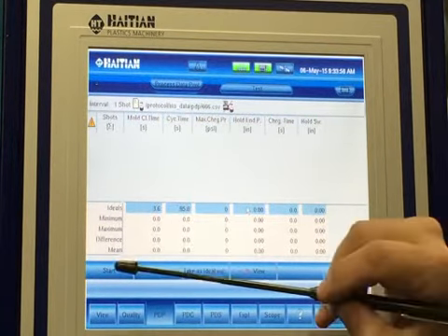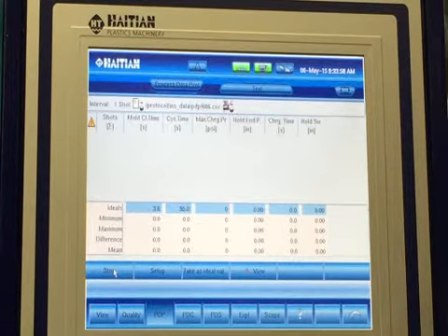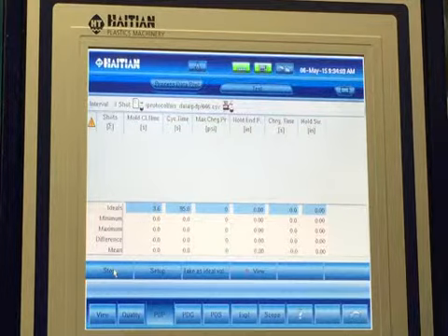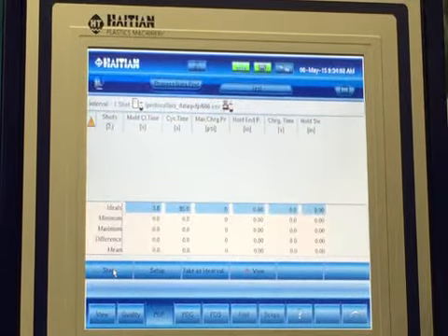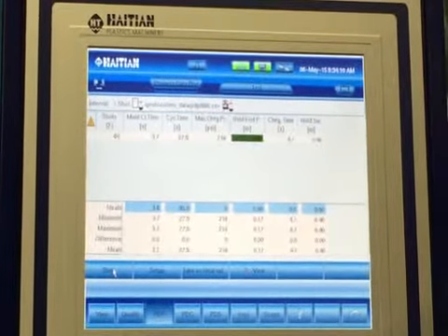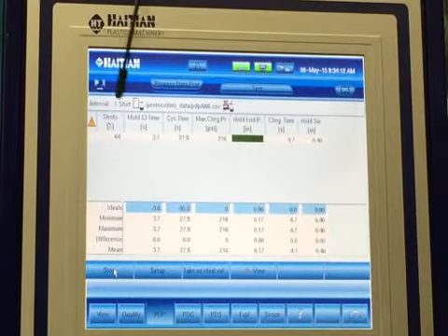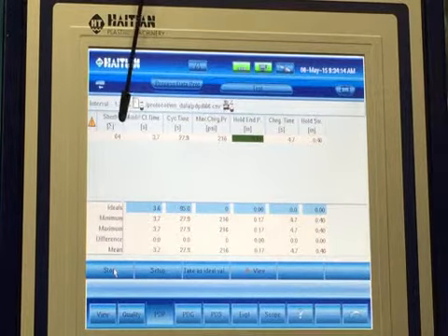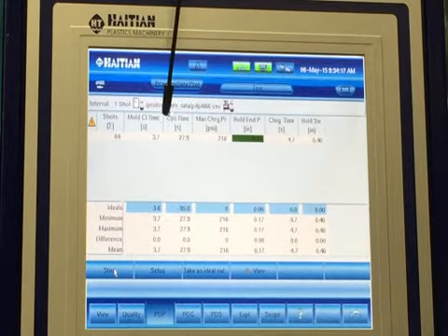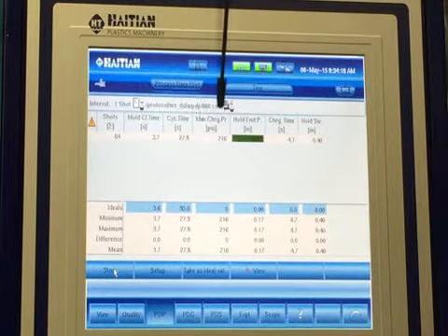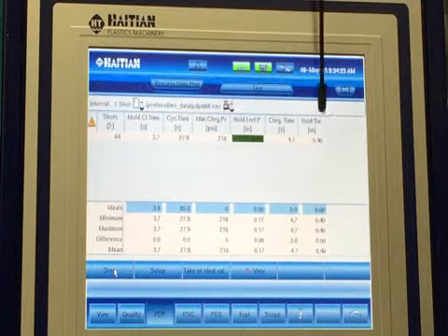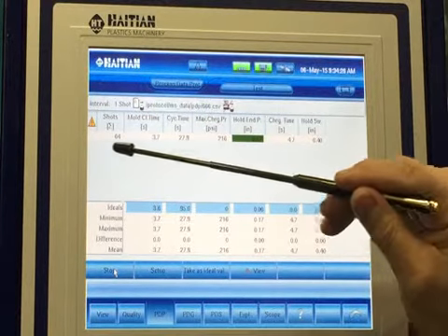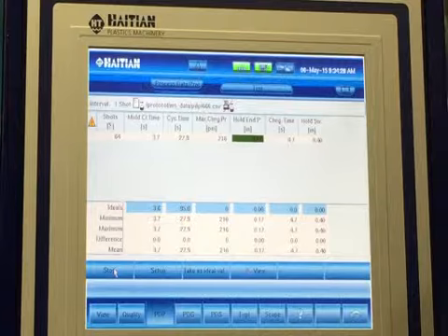First, you have to start it. So now you notice that now that it's started, this was shot number 64, the mold close time, the cycle time, the charge pressure, the end position, the charge time, and the hold switch are all listed on there now.